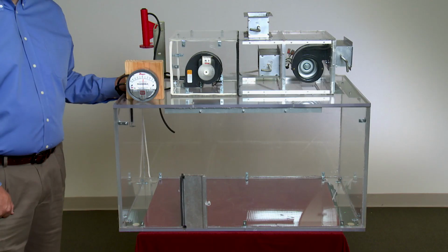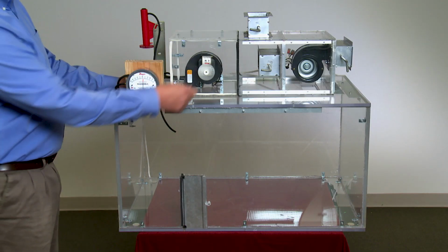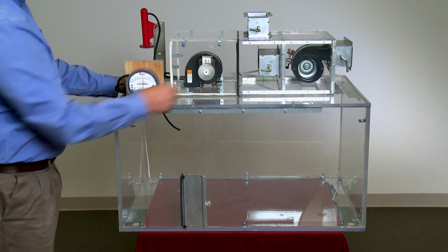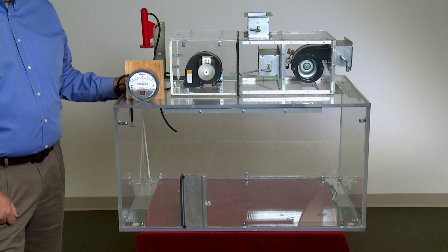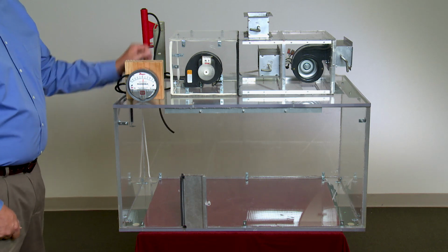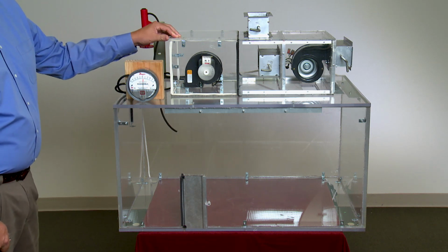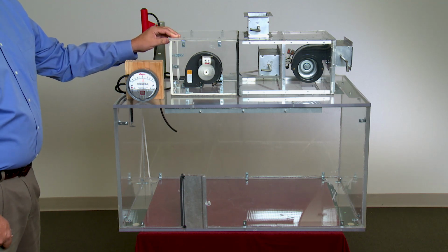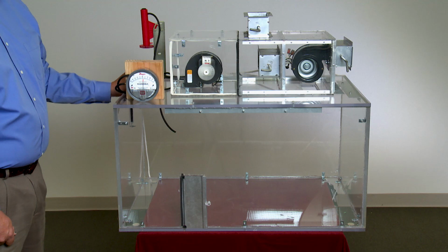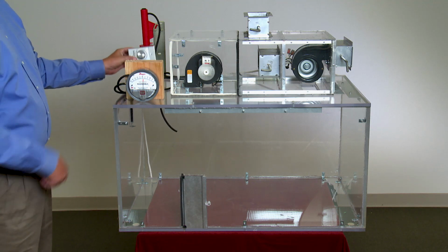John and Eric will demonstrate. We still have the same configuration as before, with a relief fan that's used to force excess air out of the building. For this demonstration, both the supply fan and relief fan are already running, with the outdoor damper open to minimum ventilation position. Note that each fan has a knob we can use to vary its speed so we can mimic VAV operation.